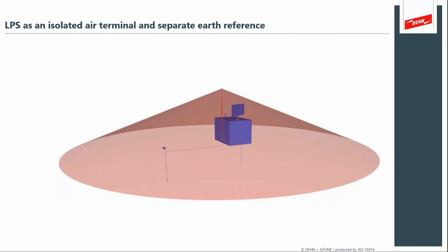What's nice about this photograph is this illustration, it shows exactly the concepts that we've been talking about. You've got a lightning air terminal up above the victim equipment. In this case, it's a radar type of a shelter, for instance. And what you've got is the calculated angle of protection. This is one of the alternate methods. It doesn't always have to be a rolling sphere calculation. In this case, with a single air terminal, you can calculate the angle of protection. Essentially, the things that are below this angle are considered protected. And this is what you see in the standards called the zone of protection. And you can build a more and more robust protected zone.